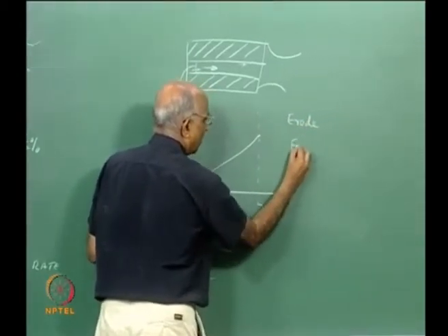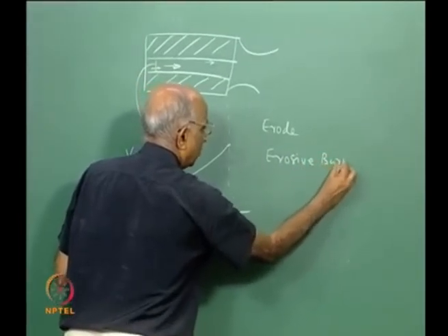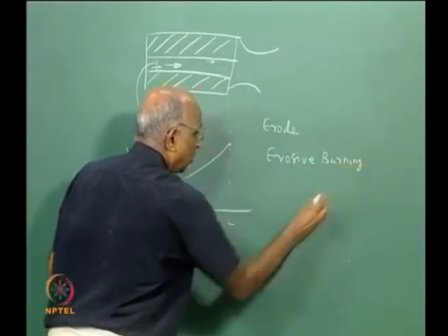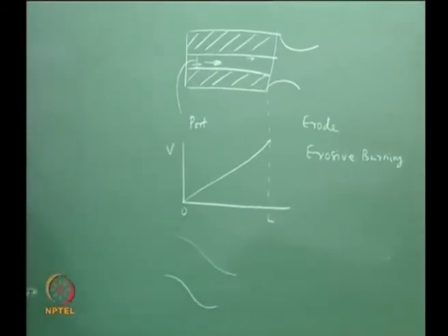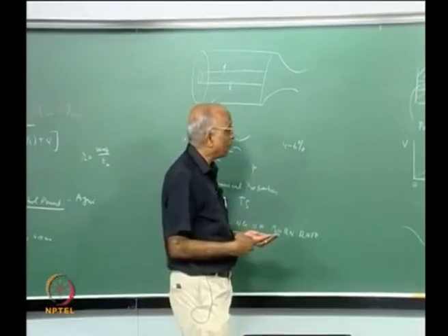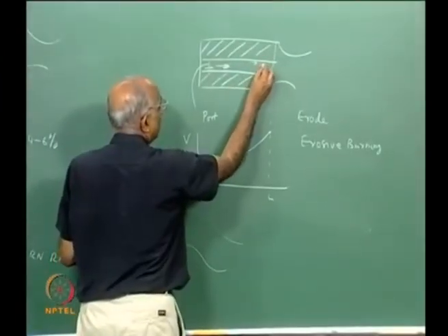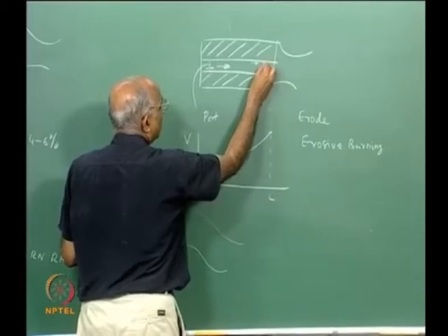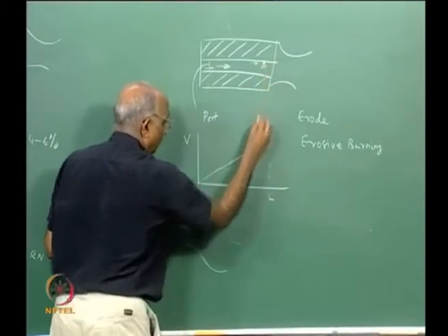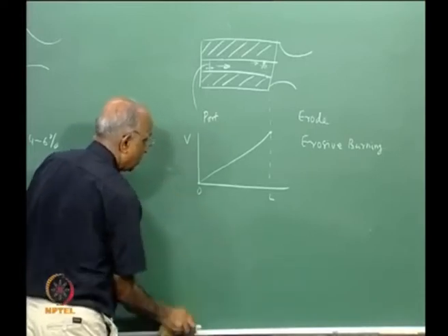In other words, I could have something like erosive burning. Mind you, propellant was a heterogeneous composite, so it is sort of eroding the surface, but more than erosive burning, I find velocity here is higher, therefore my Nusselt number or my Reynolds number at the point, let's put it down, let's now write it.